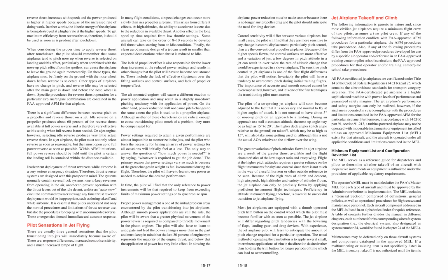The MEL serves as a reference guide for dispatchers and pilots to determine whether takeoff of an aircraft with inoperative instruments or equipment is authorized under the provisions of applicable regulatory requirements. The operator's MEL must be modeled after the FAA's master MEL for each type of aircraft and must be approved by the administrator before its implementation.